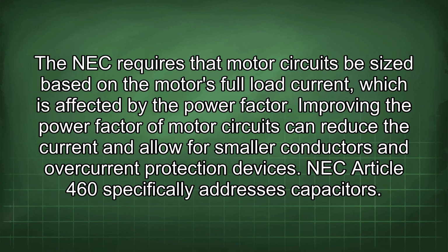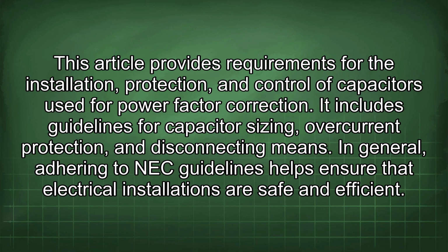The NEC requires that motor circuits be sized based on the motor's full load current, which is affected by the power factor. Improving the power factor of motor circuits can reduce the current and allow for smaller conductors and overcurrent protection devices. NEC Article 460 specifically addresses capacitors. This article provides requirements for the installation, protection, and control of capacitors used for power factor correction. It includes guidelines for capacitor sizing, overcurrent protection, and disconnecting means.